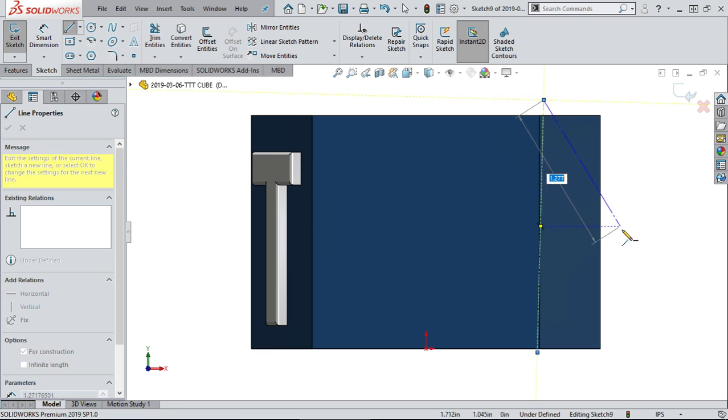If I want to make a line here that's not quite to the midpoint, I don't want to have it snap. I want it to be right in between these two points, but it keeps snapping to one or the other. Well, I can just hold Control there. And now I can drop that point wherever I want without picking up on that inferencing.